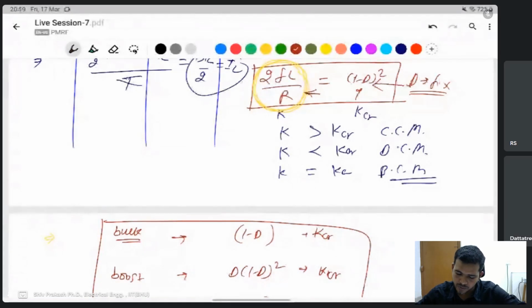Frequency compensation, whatever we have made, error amplifier and compensator, whether it is voltage mode or current mode, if I design a control system, the controller will work. The converter will work, but it depends on the inductance value. If your frequency is fixed, the inductor is also fixed. Then the converter works in continuous or discontinuous conduction, but the way it is controlled is a different thing.